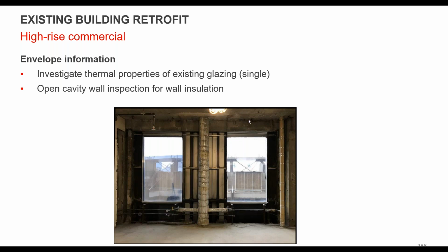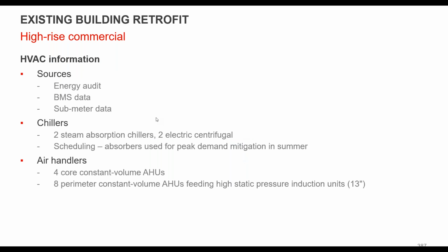the floor to floor slab basically extends all the way out past the thermal plane, and it's basically a thermal bridge to the outside. I'll show you what the new version looks like when we get there.